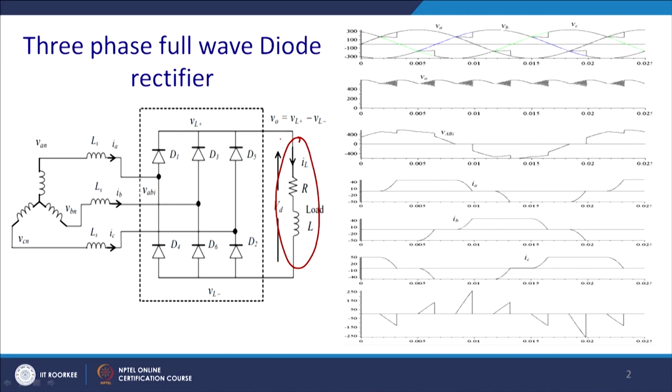We shall continue today, first with the remaining part on the source inductance, and then we shall discuss the PWM rectifier in detail. So, let us go back again. In this configuration we talked about the RC load, now we talk about the RL load, and we have some amount of source inductance placed. It may be due to the leakage reactance of the transformer, or any external inductance added, or even the line has its own inductance.